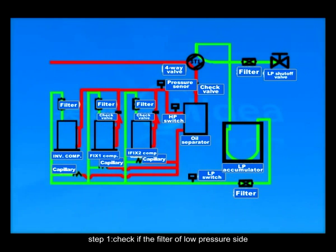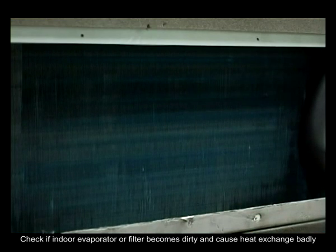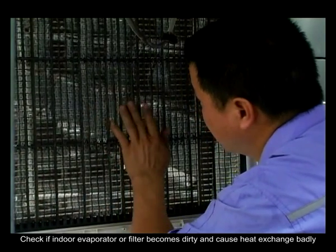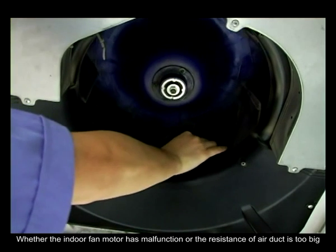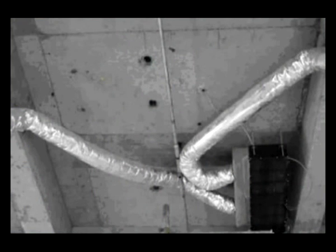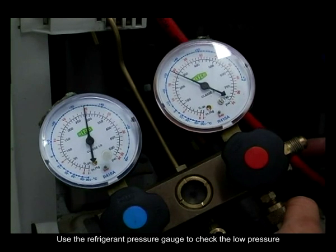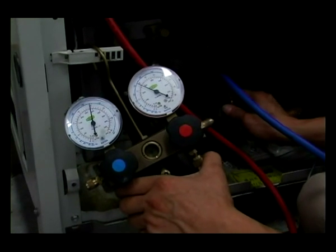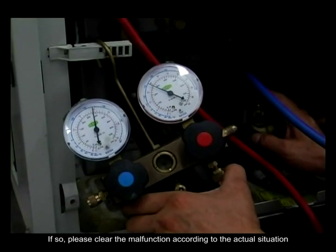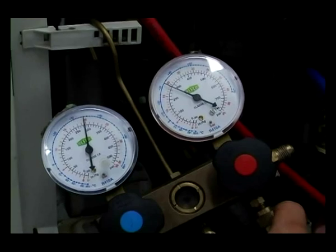Step 1. Check if the filter of low pressure side or indoor electronic expansion valve is jammed. Check if the indoor evaporator or filter becomes dirty and causes bad heat exchange. Check whether the indoor fan motor has a malfunction or the resistance of the air duct is too big, which causes air volume smaller than normal. Use the refrigerant pressure gauge to check the low pressure. If the pressure is too low, the above situation can exist. If so, please clear the malfunction according to the actual situation. If not, please go to the next step.